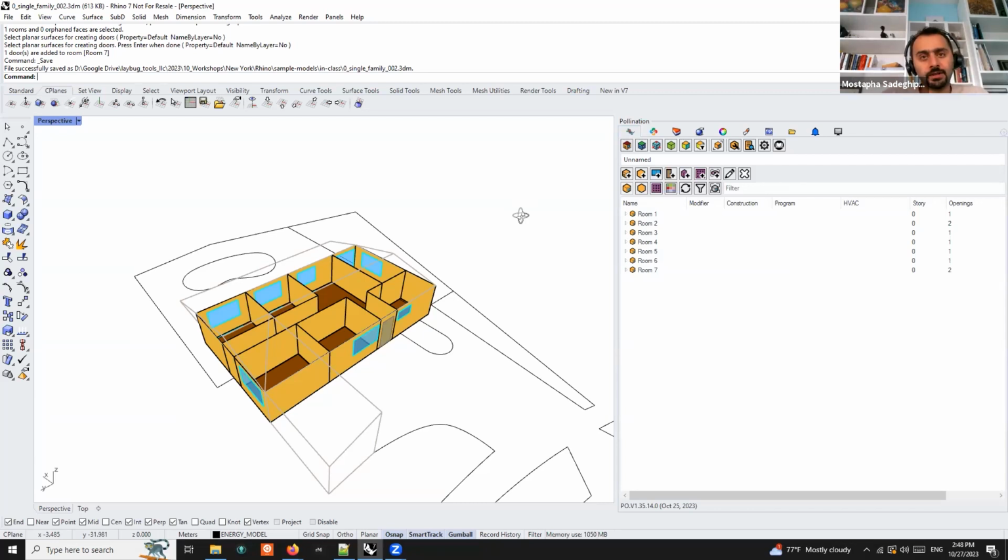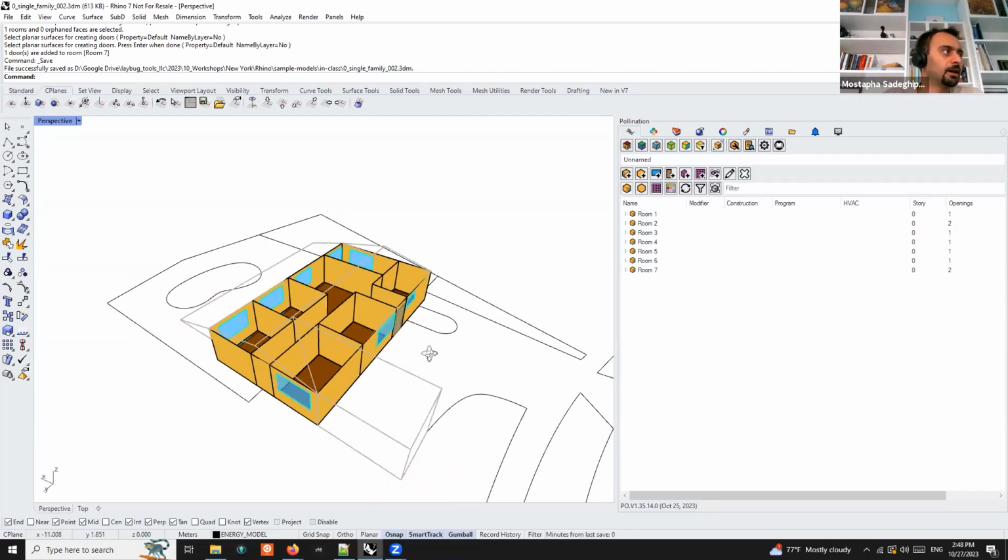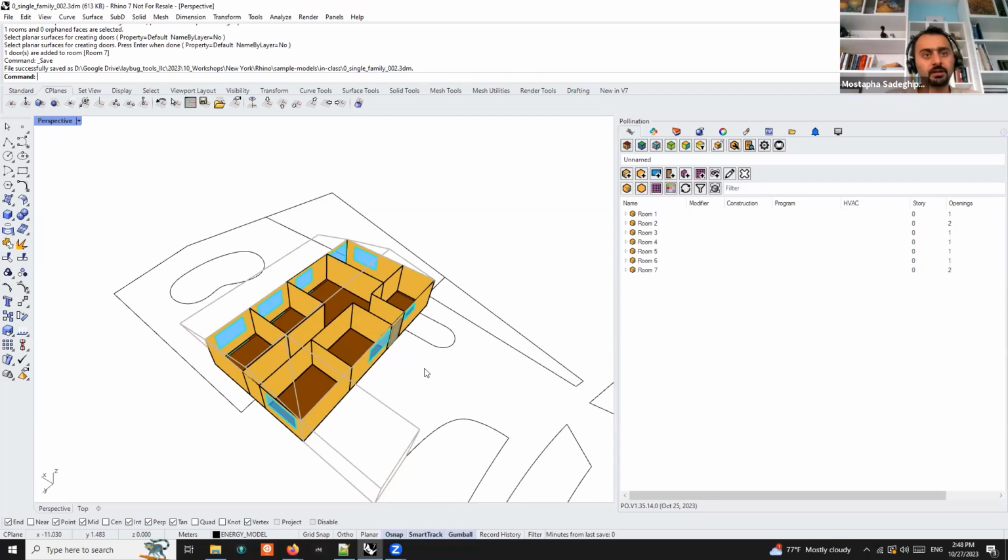Okay, now that you have this, by now you should know what's the next step. It's to run solve adjacency or run validation, depending on where you want to check. If the model is a mess, I usually run validation before solve adjacency, and then I run it after solve adjacency, because you want to make sure everything works.